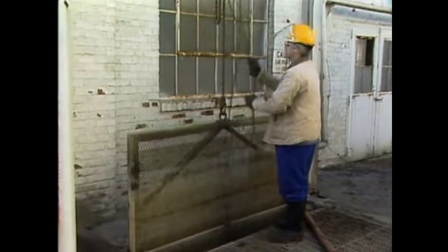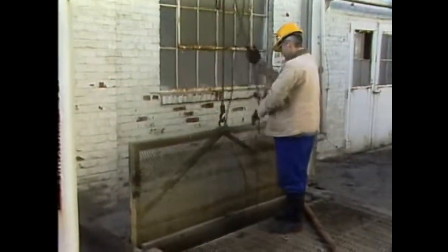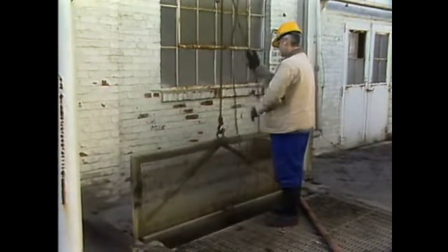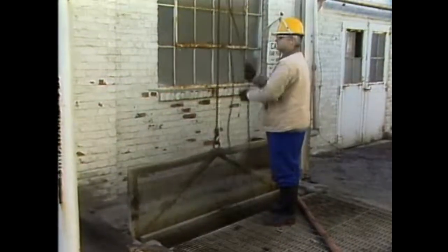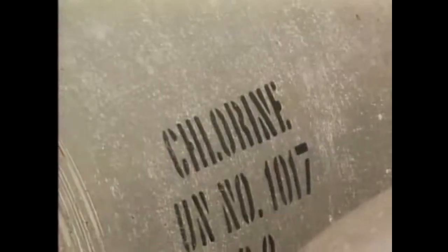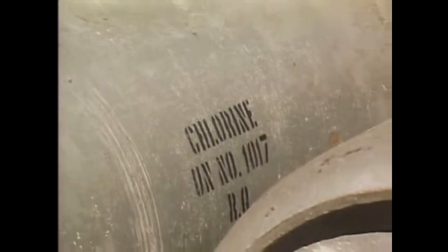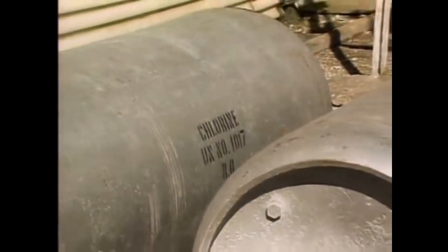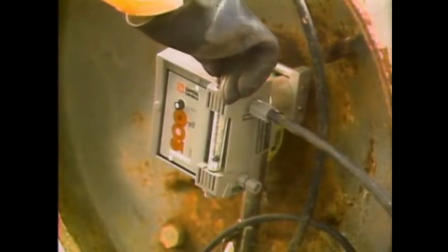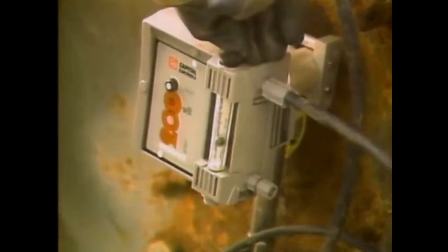Different techniques can be used to minimize fouling. For example, filters and screens can be used to remove particles from the fluids before they enter the heat exchanger. Fouling can sometimes be minimized by adding chemicals to the fluids passing through a heat exchanger. For example, chemicals such as chlorine are often added to cooling water to reduce the amount of algae or other organisms inside a unit.